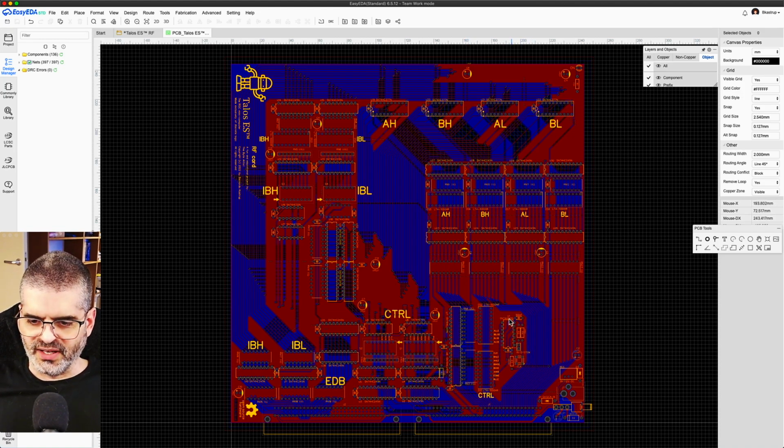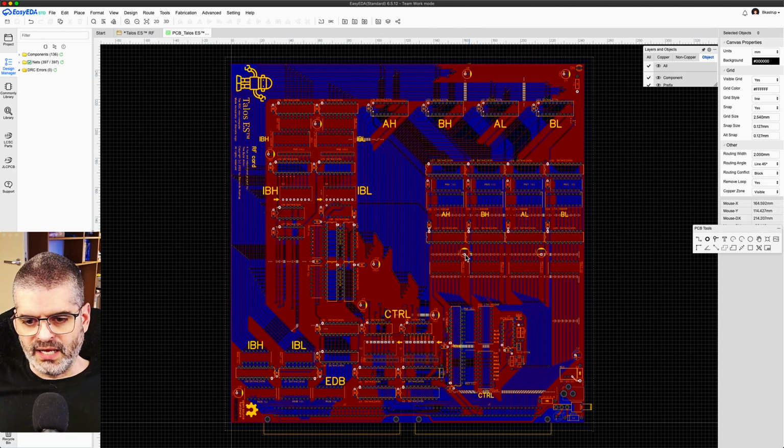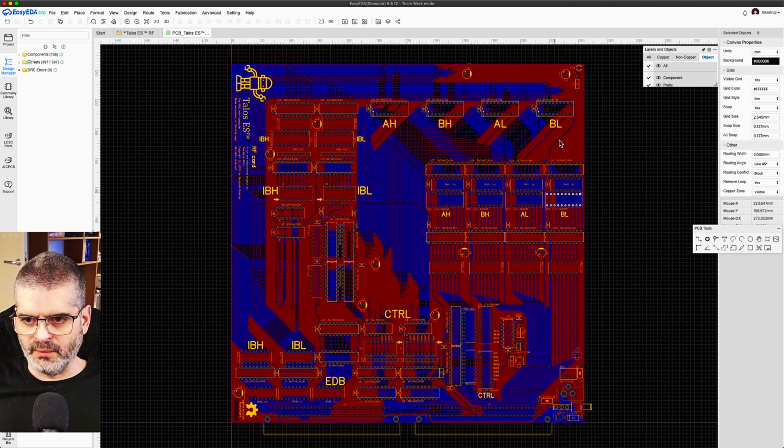And this on the side here is just the logic that we use when the board is used in standalone mode. There is a little button there for the clock. There is a little debouncing circuit and a header for us to decide whether the board is in standalone or in system mode. And here on the side, it's just the simple power supply, which is exactly the same as we discussed before. Now, the 10 electrolytic decoupling capacitors are distributed across the board.